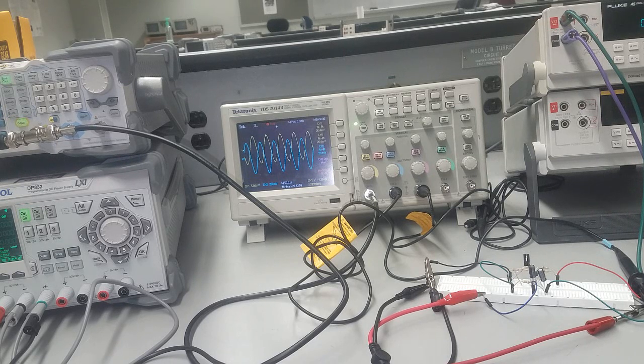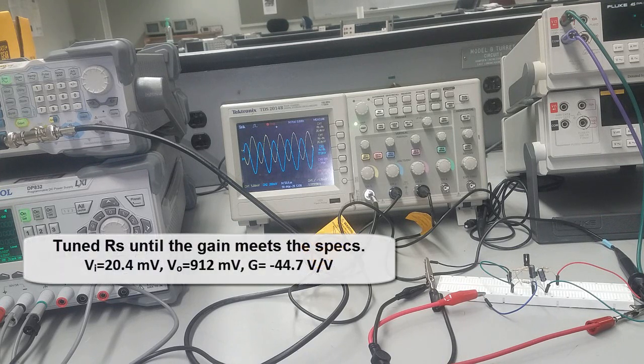Then we said let's increase the drain current a little by choosing a value for RS between 10K and 20K. So we added another 6.8K ohm resistor in series with the 10K, which makes it around 16.6K.